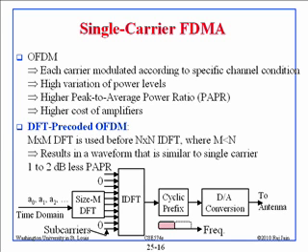Then we do an inverse discrete Fourier transform, which is N by N, and we connect these M outputs to some M inputs. It doesn't have to be the middle M or anything like that. This could be any M values out of N, right? That comes out in the time domain again. So this was in the time domain, this in the middle is in the frequency domain, see, it says subcarriers. Now after the inverse it becomes time domain again. Now we do the cyclic prefix and whatever else we need to do, and depending upon where we connect these pins, the spectrum will be either here or in the middle or something like that.